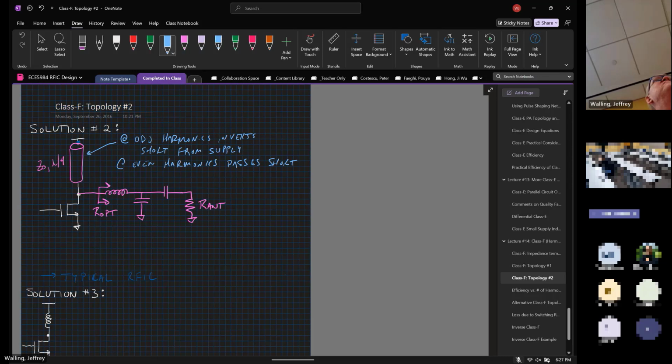You still have a problem with the lambda over 4, because you would need to do it with a wire, since you cannot do it on chip. Yeah, so this is maybe a little bit better in that it's in the supply network. If I wanted to, I could wire bond the drain of the transistor directly off chip, and then put a quarter wavelength line on a PCB or something like that. So it's a little bit better, but functionally it's still the same problem. This is going to be a long transmission line. Is there a way we can make the wire bond itself cut?